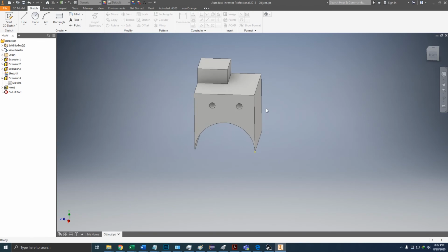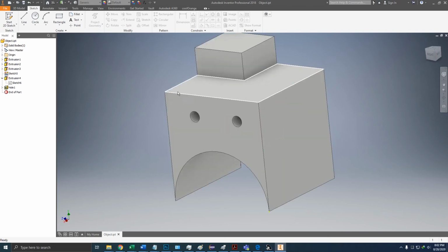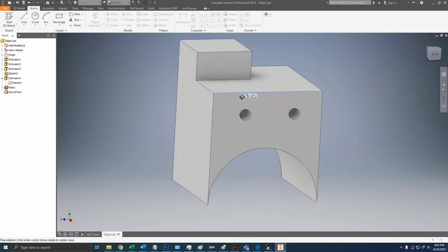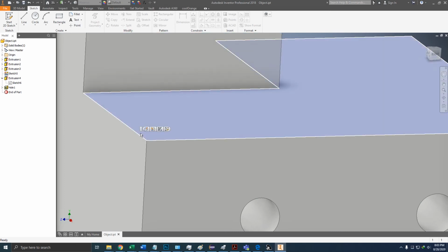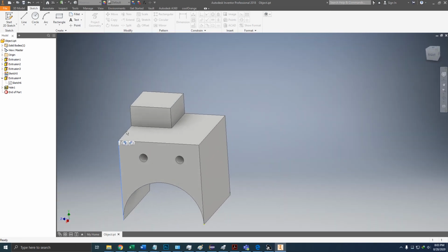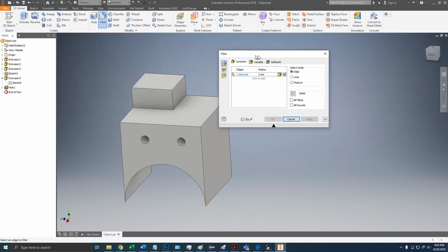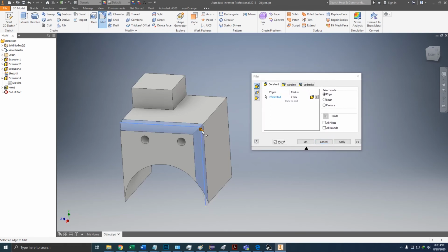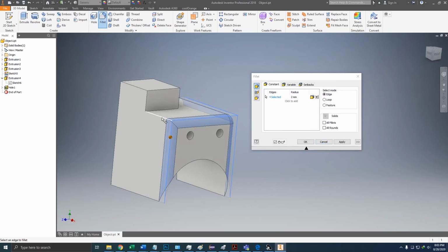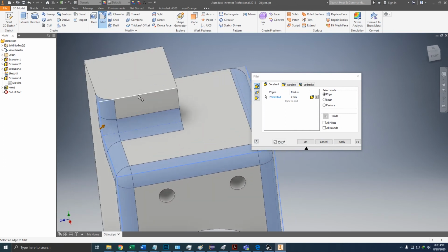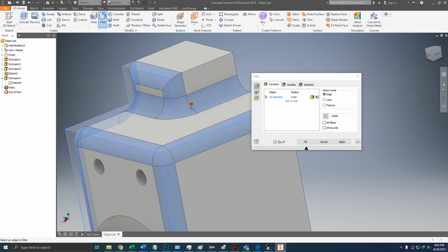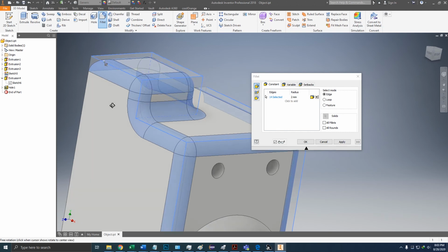Finally, I'm going to be showing you how to do a fillet. So basically, it's just rounding the edges of your model. So let's say I want to 3D print this model or make it look a little bit nicer. You can see that all the edges are really sharp. So to fix that, there's an option to round them. It's in 3D model fillet. So what this does, you select edges and it automatically smooths everything out. So sometimes when you're 3D printing, you don't want sharp edges, and you just go through all of them and make them smooth.